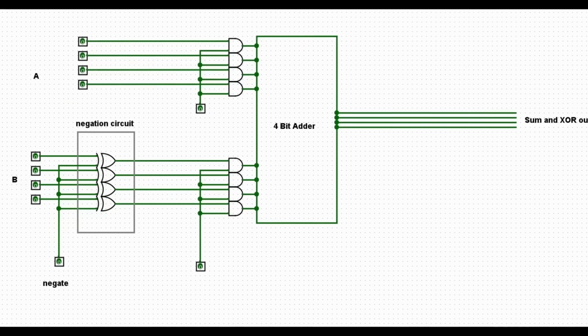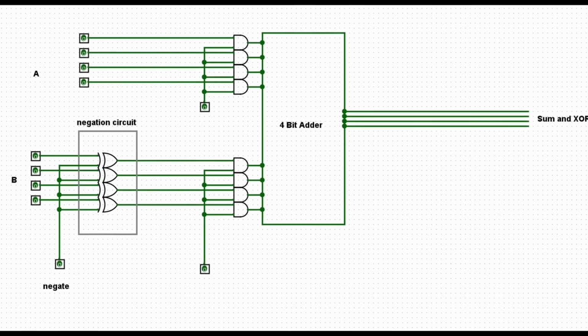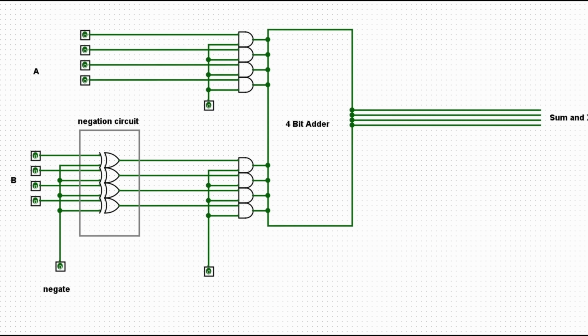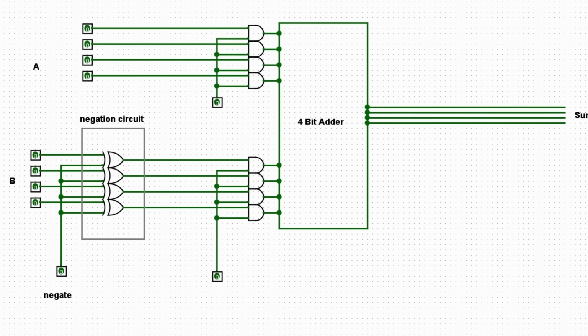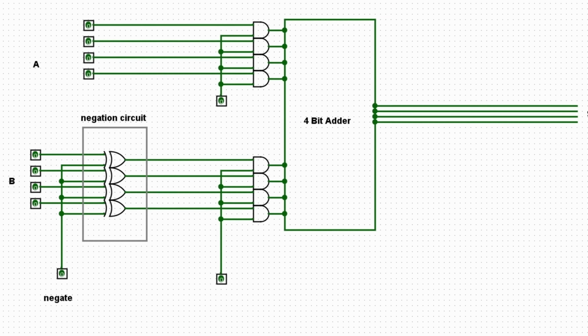That handles negation, but what about adding 1? You're right. That's why our first adder has a carry in signal. We could just add 1 through the carry. Now we can add, subtract, AND, NOR, and XOR. One more clever addition would be the ability to send in 0 to either input. This will allow us to see the value stored in the registers without having to add a bunch of logic circuitry.